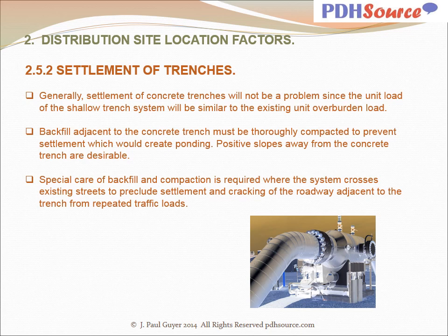With regard to settlement of trenches, generally, settlement of concrete trenches will not be a problem since the unit load of the shallow trench system will be similar to the existing unit overburden load. Backfill adjacent to the concrete trench must be thoroughly compacted to prevent settlement, which would create ponding. Positive slopes away from the concrete trench are desirable.